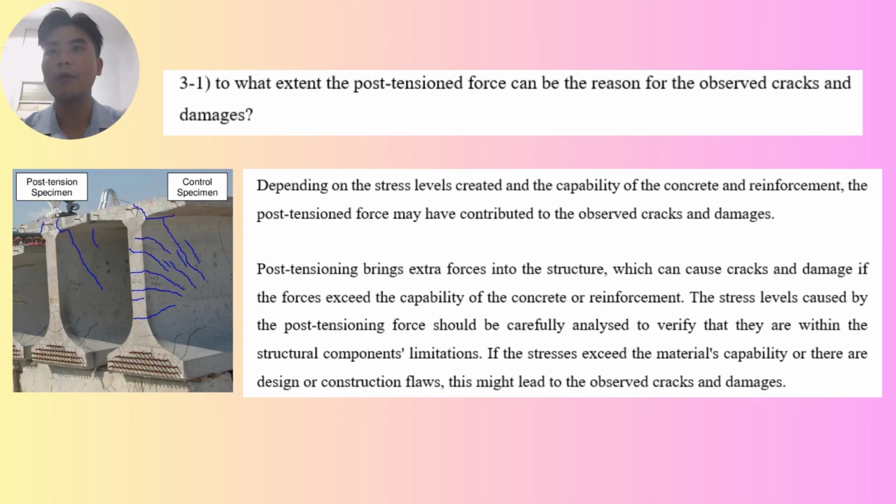Hi, I'm Xavier and I will be answering question 3.1. The reason for the observed cracks and damage caused by the post-tension force depends on the stress level created and the capability of the concrete and reinforcement. The post-tension brings extra force into the structure, which can cause cracks and damage if the force exceeds the capability of the concrete or reinforcement. The stress level should be verified within the structural components' limitations. Once the stress exceeds the limitation, or there is a construction flaw, it will cause the observed cracks and damage.